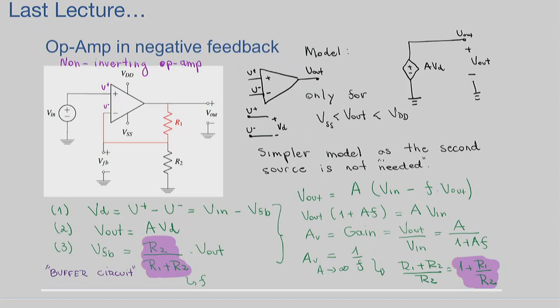And then we finished by saying, okay, if we use this operational amplifier in this configuration, where we used our good old voltage divider as the component that provides the negative feedback signal, we can take a portion of the voltage, because we know that the voltage divider divides the voltage, and feed that into the amplifier.